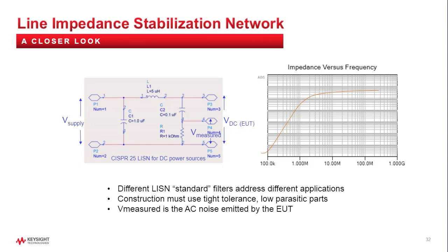Well, I definitely don't want a series cap here because I do have to pass DC. And so remember, this is between my supply and my DUT. So I'm attaching a battery to the device. I need a DC path. But this does have a high-pass topology. So I personally would stick with the specs because the specs describe exactly what this has to be in the values. There's nothing fancy about this.